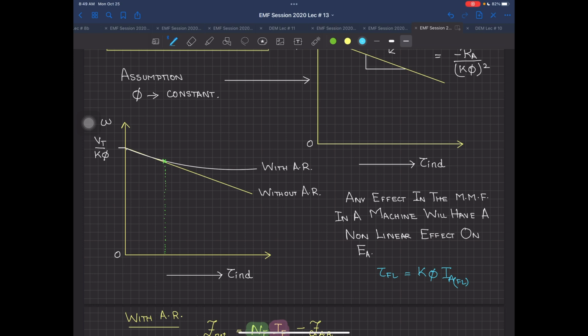You have the equations with you. You just have to do a little reverse engineering and find out what the torque is over there. It's not written on the nameplate, and no manufacturer in the world is ever going to write down the torque of your machine. They are only going to tell you the horsepower, or the input power of that machine. They are never going to tell you the torque in exact Newton meter values. They will say this is the horsepower of the machine, and assuming an 80% or 90% efficiency, you can assume the output value.